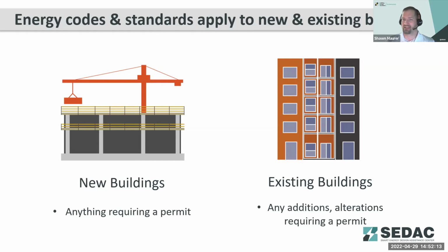If you're adding insulation to the roof in order to meet the minimum requirements of the energy code, it's not going to require you to adjust the height of parapet walls or roof curbs for HVAC systems, as those are separate components of the building. So for existing buildings, the code is set up so that you're modifying your modified sections of the building to the extent possible, given existing constraints of other unmodified portions of the building.